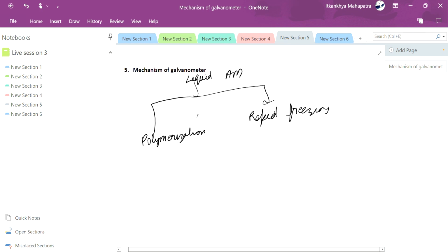Why do we use these galvanometers in the additive photopolymerization process? This is because the mass of the mirrors is very low, and hence we can deflect the mirrors at very high speed, so the laser beams can move with very high speed.